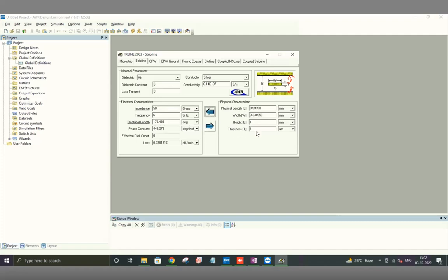So now what about the thickness? Here, unlike the case of the coaxial thing where the thing was uniform, the thickness there only contributed to the loss, because as long as you're there, the skin depth really doesn't matter. If I now just say, let's say, go from 1 micron, so keep in mind the relative dimensions, right? This 1 micron is much thinner than 300 microns for the width. So this is a very thin film.